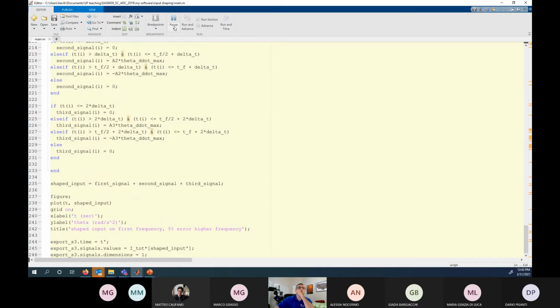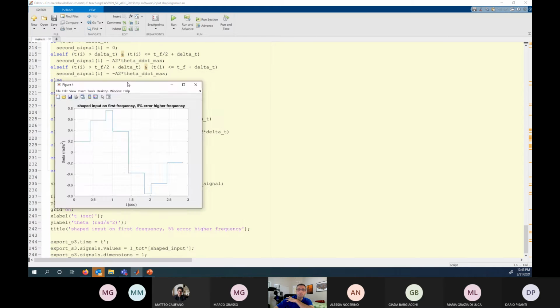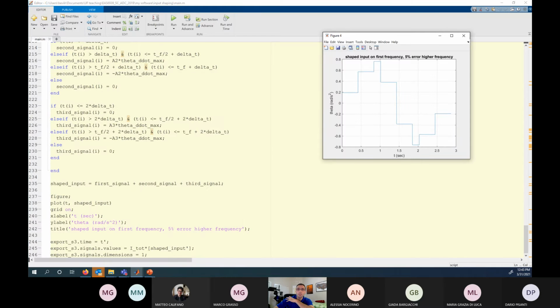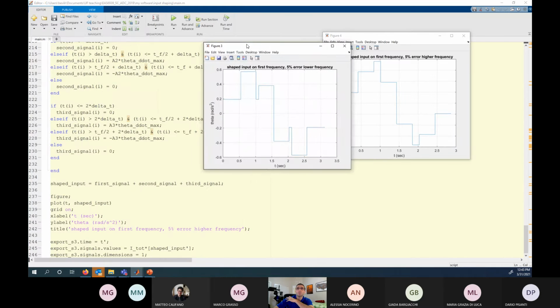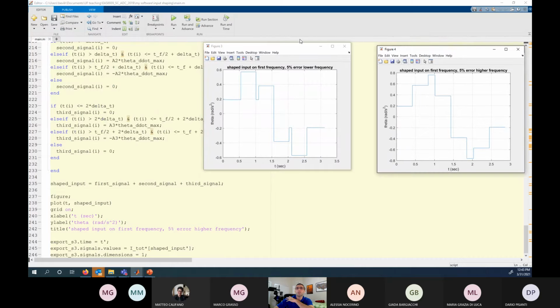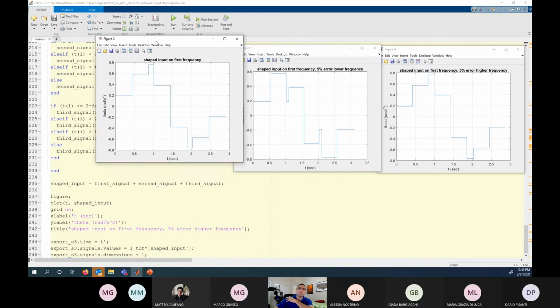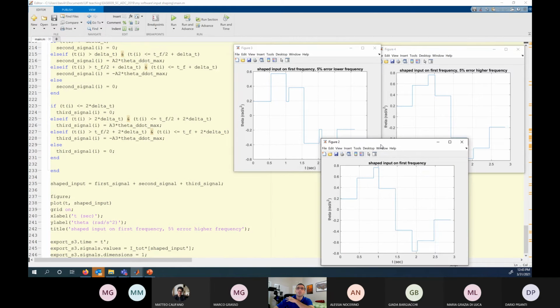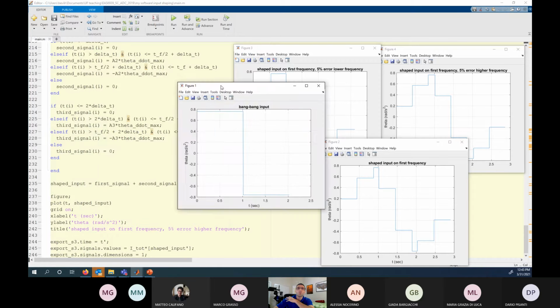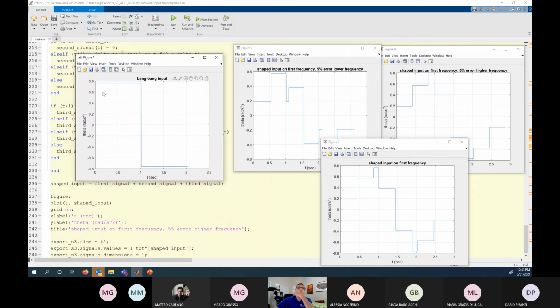If I run this, it's going to show you the different acceleration profiles, or torque profiles, that I'm going to give. Well, it's actually in terms of angular accelerations. You start from this. This was my initial signal. This is what I wanted: in about 2 seconds to reorient my hub, ignoring the fact that there is something flexible attached to it.